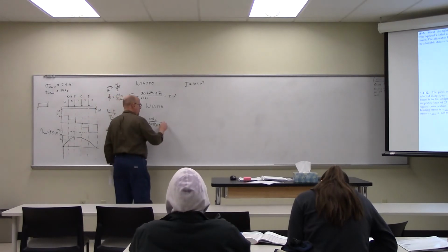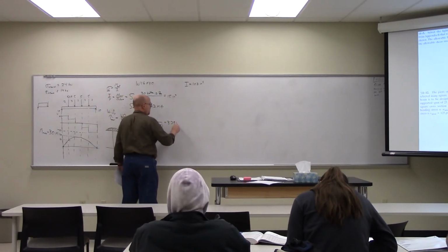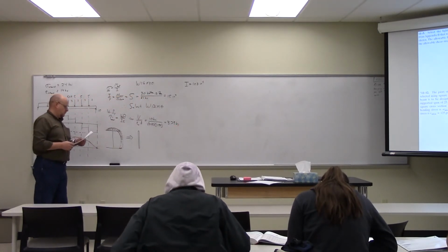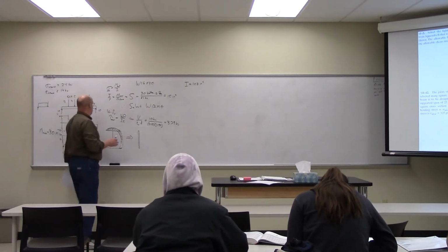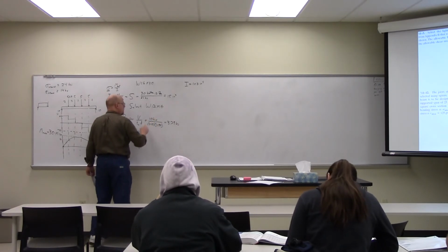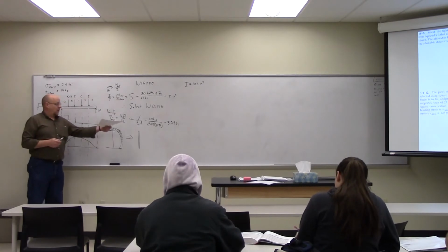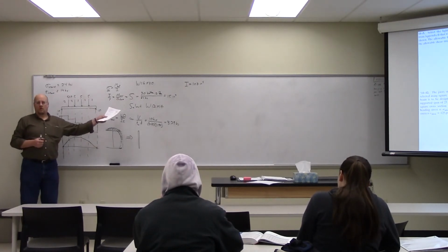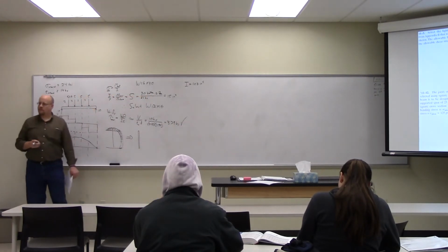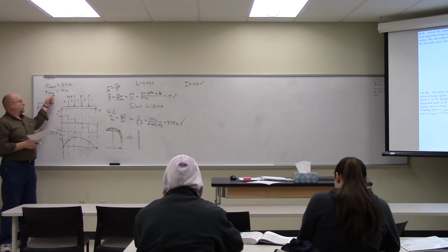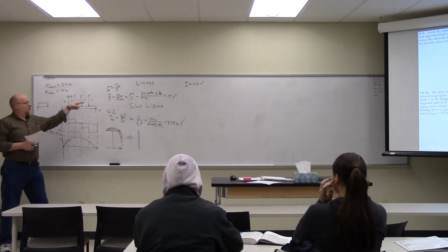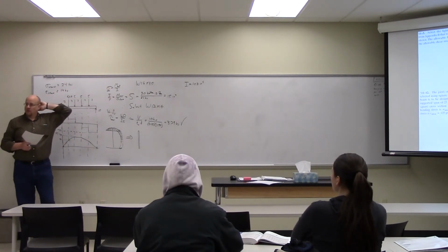So if I do that, I get 3.79 KSI. Actually, 10's not KSI, it's KIPS, sorry. These are KIPS. Okay? And so that's well below the 14, so I'm good. So I verified that indeed it is okay. And you can see how much below the 14 it is. Right, it's roughly a quarter of the allowed value when we're right at the allowed value for the normal stress.